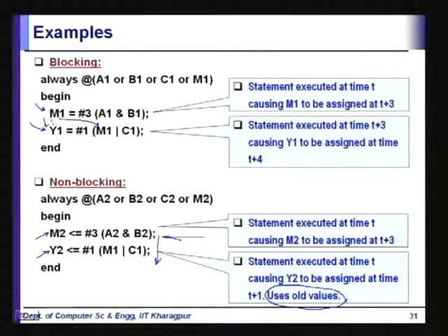See, in the blocking one, the simulator is not even going to look beyond this. It is just going to finish this and then go to the next one. It is going to block. The control will get blocked until this is done. Right? In the non-blocking, that's not the case. The control will go through to the next statement. Alright.